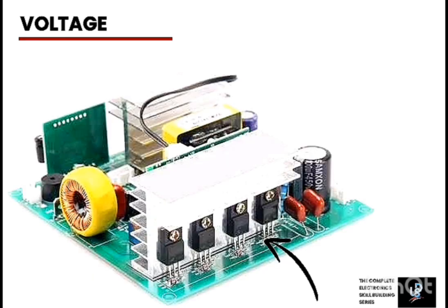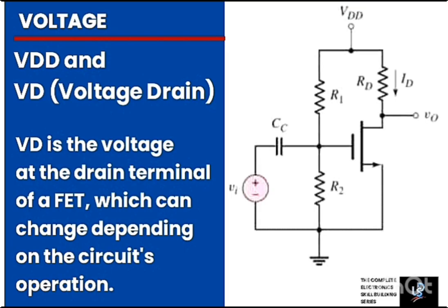Inverters use MOSFETs, which you can see here, for switching to enable DC to AC conversion. In solar inverters, the MOSFETs are turned on by a VDD range of 5 volts to 15 volts. Some may use a higher VDD range such as 20 volts to 30 volts depending on the specific application and required output voltage. Do not get confused.